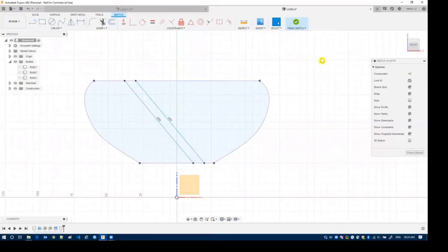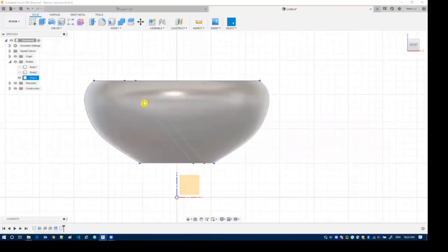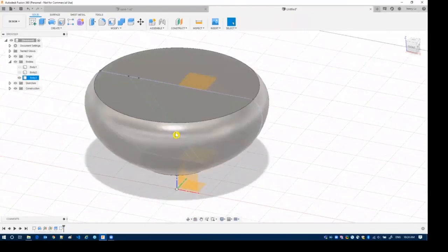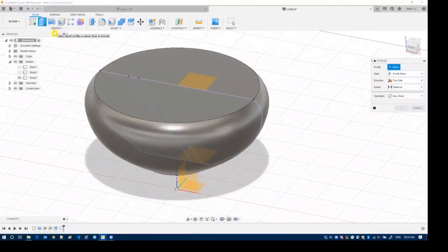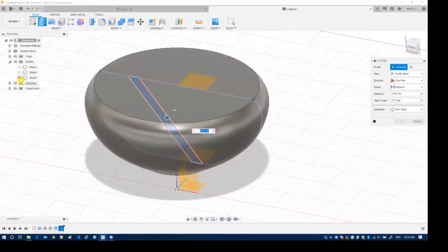All right. So now I think we can finish our sketch. Turn on the body, so we can see it's actually in the middle here. So now we need to extrude. This is just a place I want to show you how magic this extrude feature can actually be. So let's select the profile. We need to temporarily turn off the body so that I can select this one. Now turn on the body again.